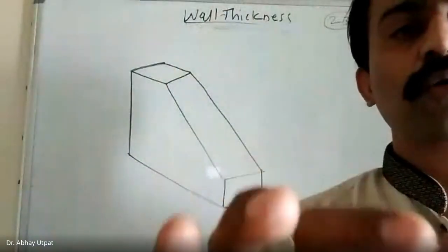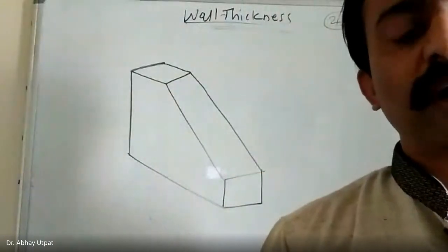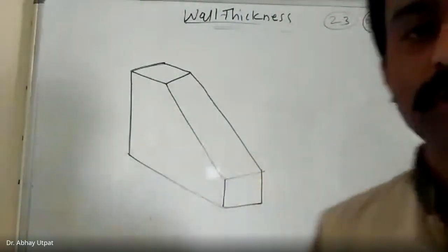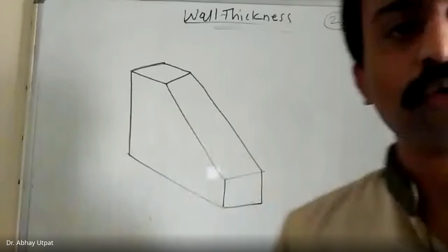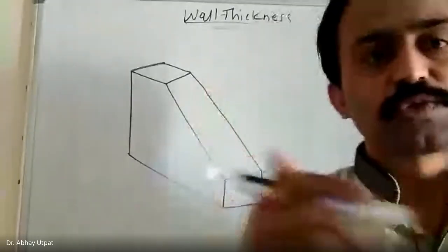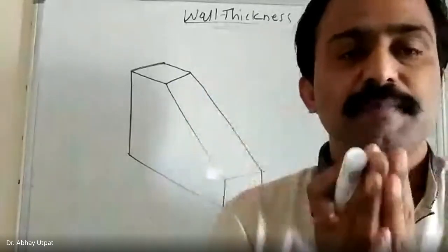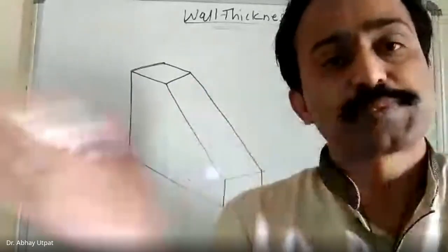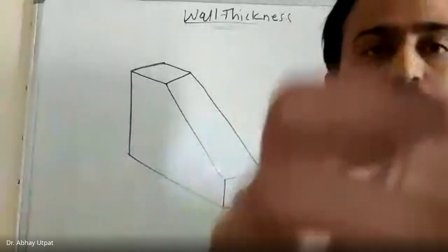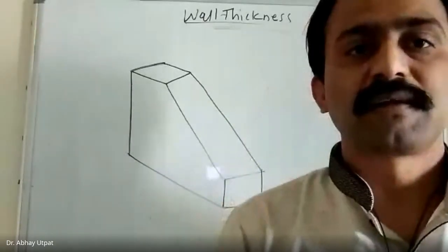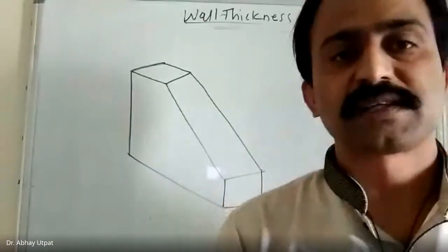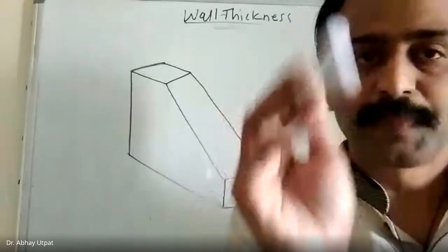Nagras: we can make it hollow. Hollow again, but from where are you going to put the core? These are molds, so it is not like sand casting. This is a metallic mold and there is a limitation of sliding cores. Both answers are 50% correct, Pranil's answer and Girish's answer.